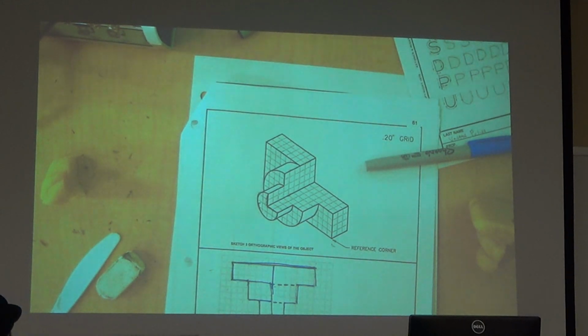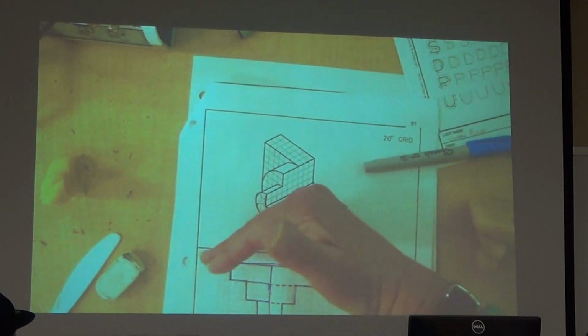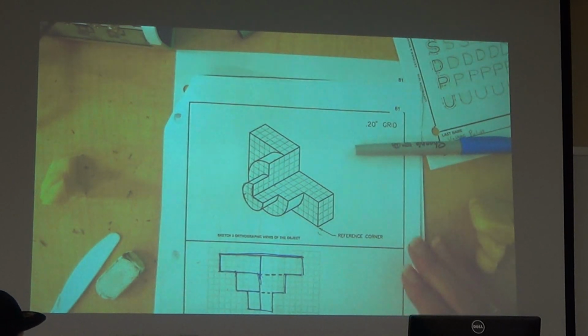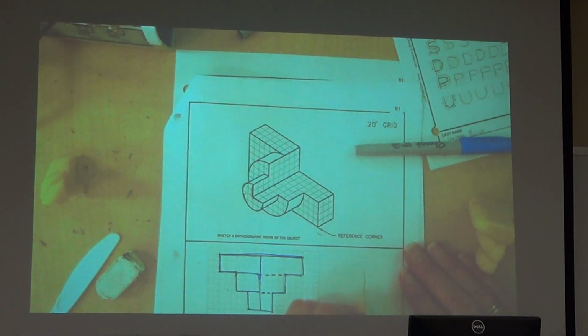Okay? But the most basic, do you remember the drawings for every single part? You should always have multi-views, and then you have your isometric here. So it shows you the 3-dimensional view, but it also shows you the details here. What else do you do with these? For mechanical drawings, you always dimension these, right? Dimensions are not on 3D drawings, dimensions are on here. So the reason for the multi-views is, one, to show a little more detail, and also to show where the dimensions are.